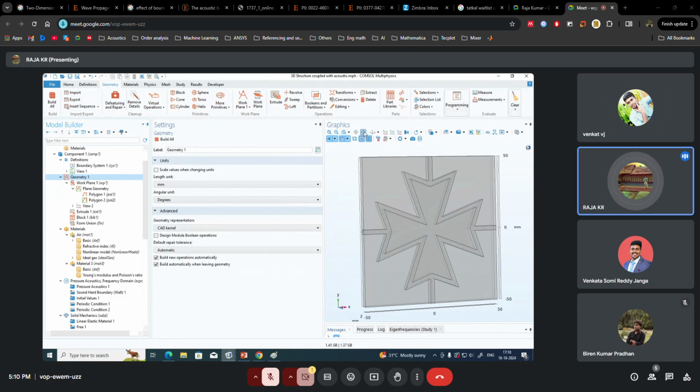Even in underwater acoustics, if you have heard of the anechoic coating or something, mostly that is rubber, which is a viscoelastic material, right? But they model it as a linear elastic material because doing the viscoelastic analytical part takes a lot of effort.